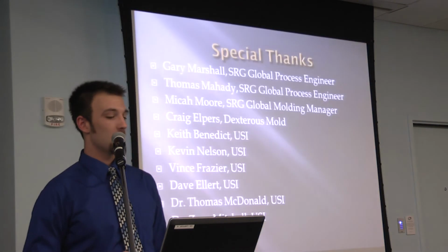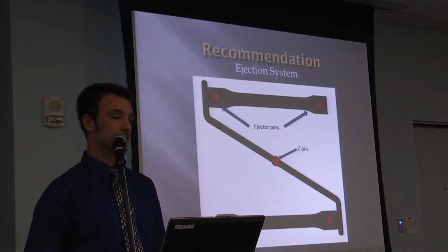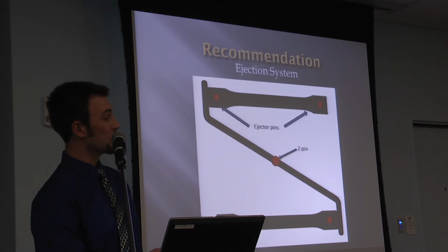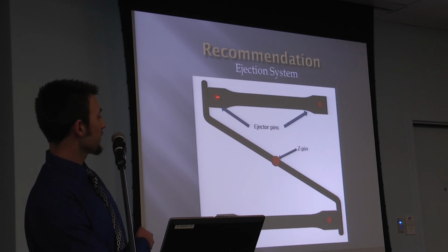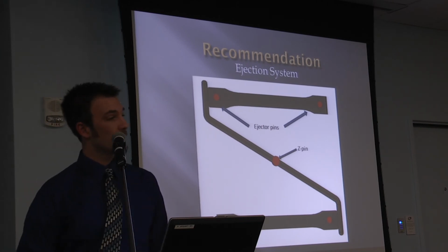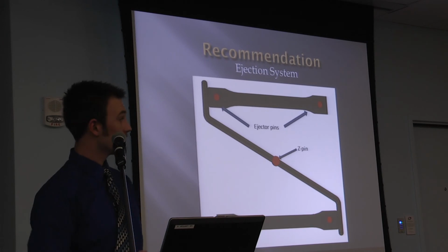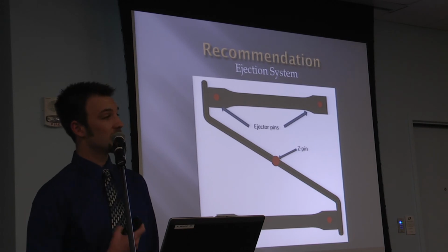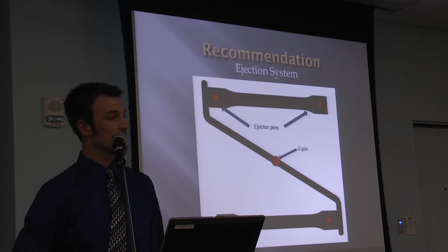On your recommended mold, you didn't show where the vents were. How were you going to vent? Are you talking about on my recommended part design? Yeah, here. We will want to put the vents at the end of each location, and depending on the different types of material, we may need a vent in these locations, so that the air is not trapped in these spots. If push comes to shove, we can actually put a vent right here and right here, but I think that venting at the end of the locations of the parts is all that's needed.